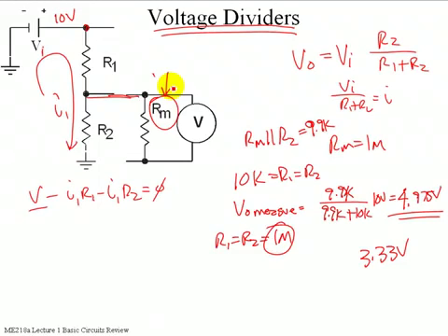You could go buy a better meter that had 10 or 100 mega ohms. And in fact, on oscilloscope probes, you can change between 1 times and 10 times because the actual current being measured inside the device is much less. And so you can flip in a series resistance to raise the resistance of the probe. But that lowers the voltage that gets measured inside, so you have to compensate for that.